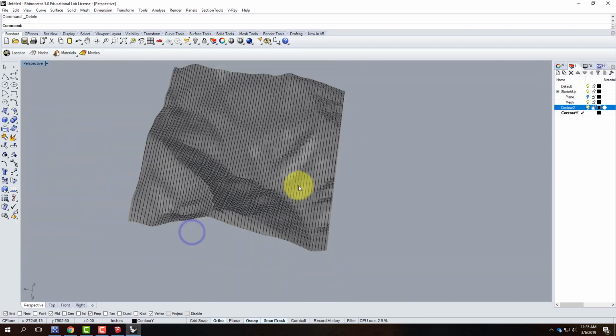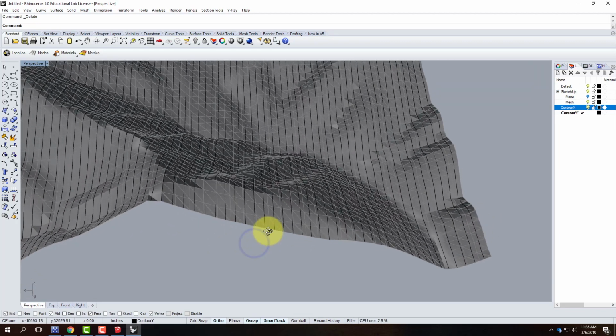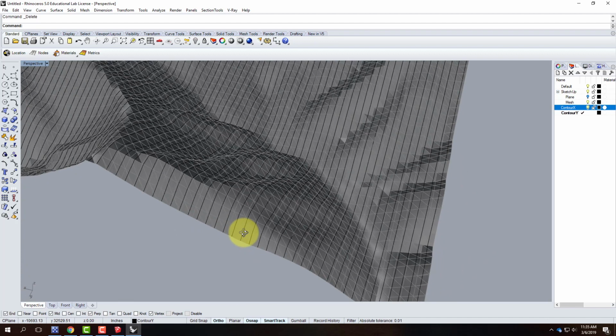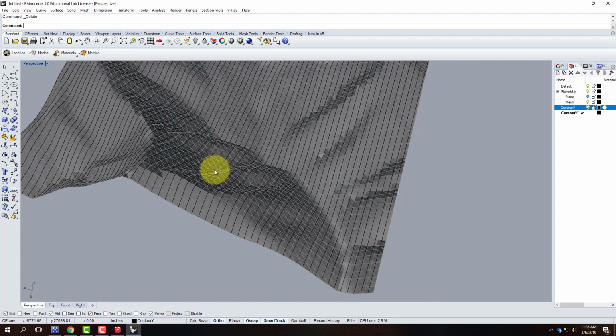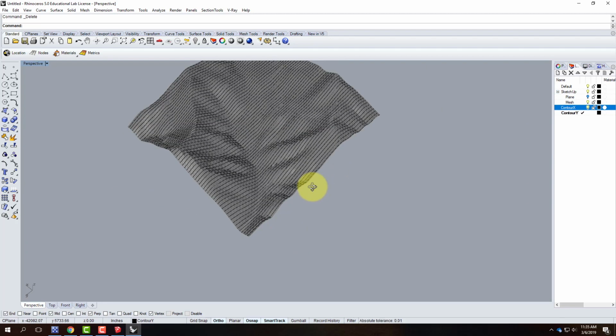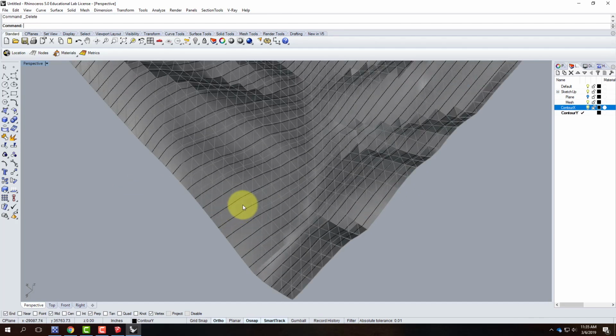The other thing, my contours were actually probably slightly narrower than I needed them to be. Remember that this is divided up into a bunch of triangles. I really only need one contour at each interval of triangle because I can't get more accurate than that. So that's how I'm determining what this is. 100 feet seems reasonable for what I'm doing. 50 feet wouldn't be close enough. We'd be losing information. So let me repeat this one more time.